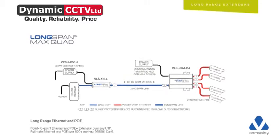I'm showing you the long span quad again, Max. This is the slide we had on before, 3 or 4 slides ago. So I brought it back now because now it's pertinent, if you like, because we did the other piece. So this is now long span light working with the Max quad. So we've now mixed and matched, whereas once upon a time we didn't mix and match our products, but now we can. So we can have that data over your 820 meters, your Cat 5, 6, 7, etc. But then if you've got the capabilities of say powering it at the endpoint, always recommend you do that anyway. But at least then out of this you've got extremely high wattages, and you've got that 71 watts to split amongst your cameras or what other device you're plugging in.